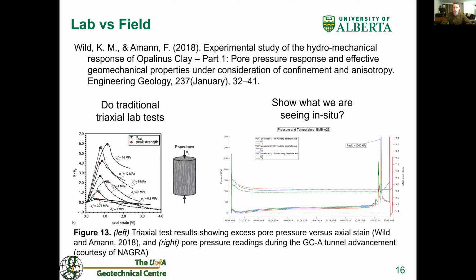As mentioned previously, we will be synthesizing and analyzing the field data from the MBA and GCA experiments at Mont Terri. We will then compare the results from the field program to our direct shear testing results. The direct shear tests will be the first to truly mimic the strain-controlled boundary conditions that exist at the tunnel face during the mine-by experiments while capturing internal pore pressure measurements. Our hope is that the internal pore pressure measurements show spikes similar to those seen during the tunnel advancement.